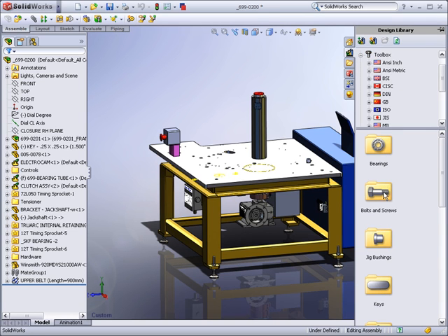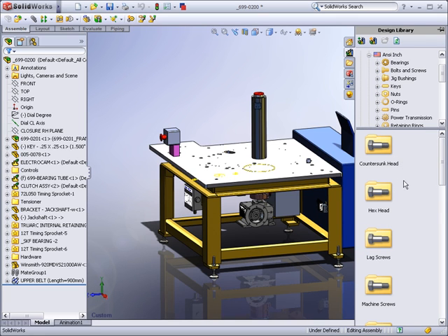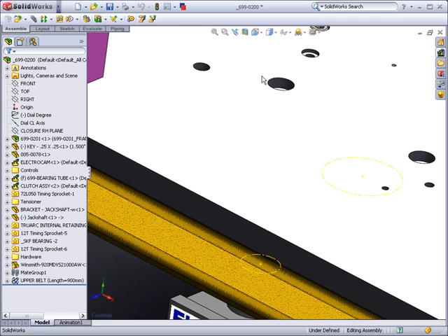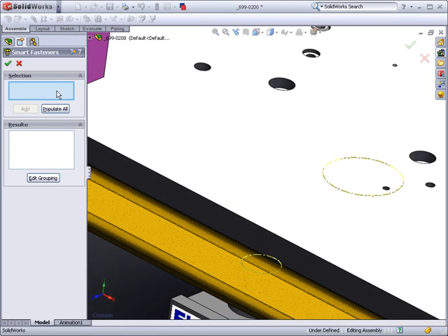Toolbox contains thousands of industry-standard fasteners and parts that can be used individually by dragging and dropping them in assemblies. In this example, we will show how SolidWorks Smart Fastener Technology makes use of Toolbox components to automatically select the correct fastener type and size for holes requiring fasteners. Here, we will add 2 bolts to fasten the support bracket to the table.